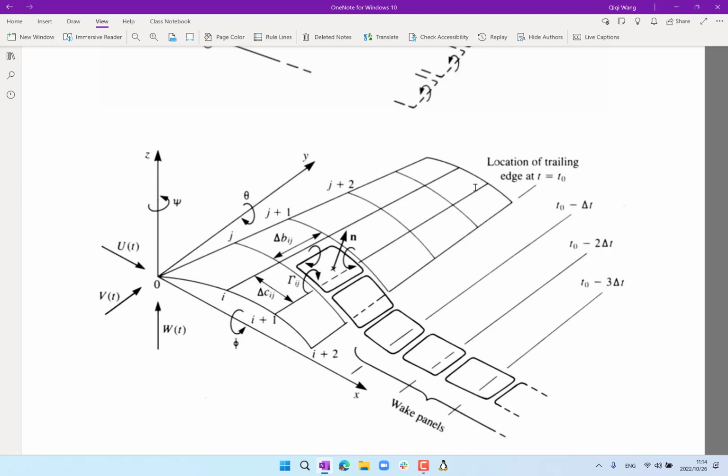But as all the vortex rings move downstream, this airplane wing is continuously generating new vortex rings. It's like literally the wing is like a dolphin spitting vortex rings in the downward direction in a continuous way. And how much vortex ring it spits down per unit time is computed by how much lift, what is the circulation around the airplane wing.